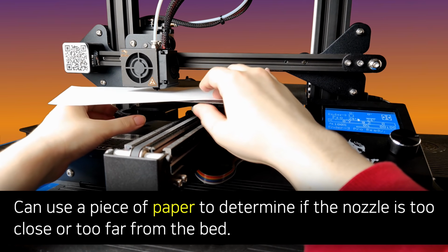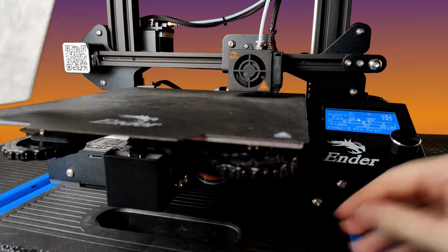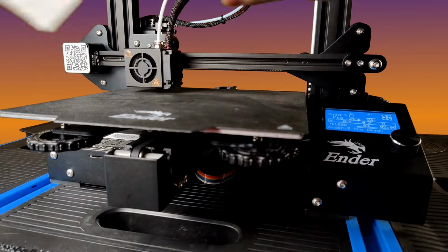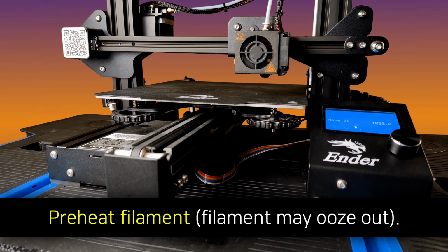get from putting a piece of paper between the nozzle and the printer bed. Ideally, I'm trying to make it so that the nozzle is lightly scratching the paper. So there shouldn't be too much resistance, but the nozzle should also be touching the paper. After that, I moved the printer head up on the Z-axis, and then I started preheating for PLA filament.